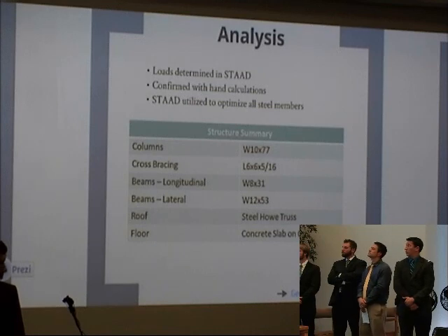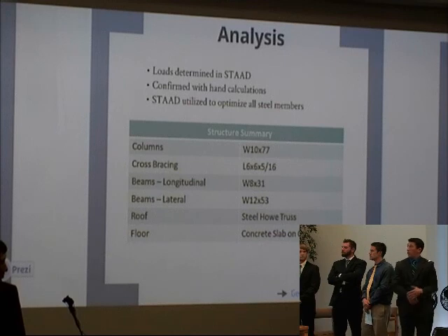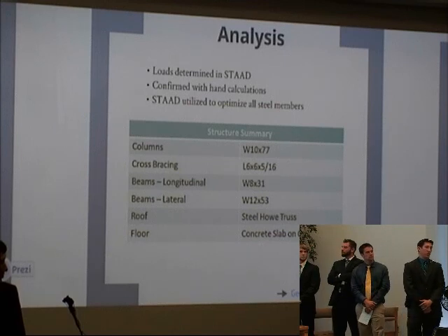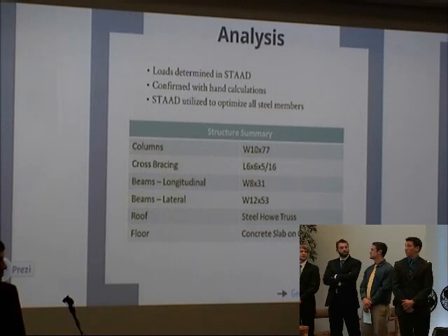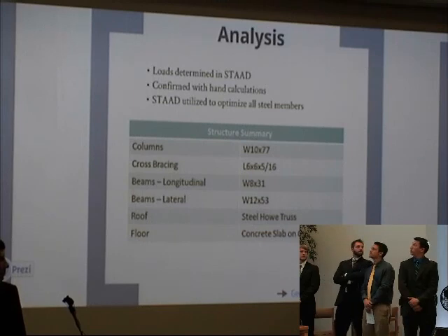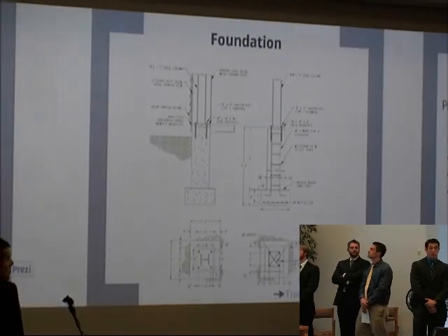The table here shows another summary of the structure. And also in the STAAD output, we were able to determine the reaction loads and nodal displacements, and this helped us to find the column loads to pass on to the geotechnical team. And I'm going to pass it on to Rob to talk about the foundations for each of the buildings.